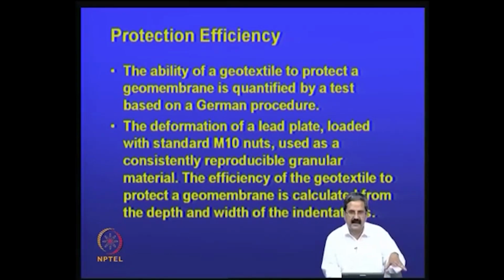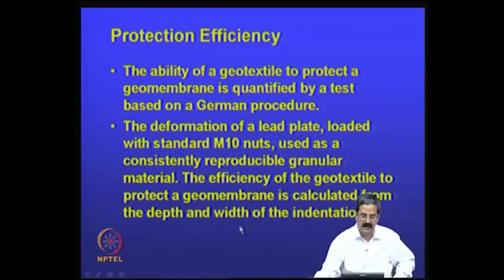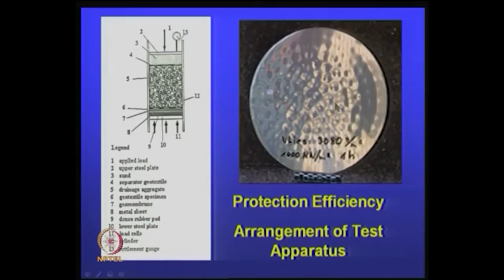As I just said, landfills have to have a geomembrane. The geomembrane is a very important thing, because the permeability is very low due to the geomembrane, and if the geomembrane gets punctured, then it is a problem. So, people have what is called a protection layer. It is a simple experiment that they do, and I will show you that. This is a type of test they developed.